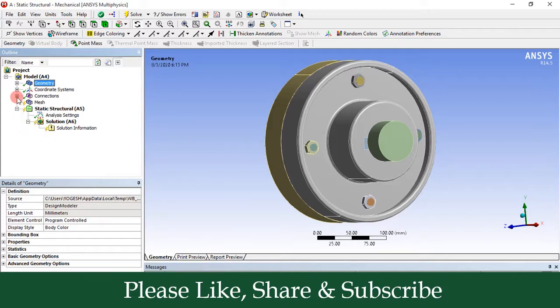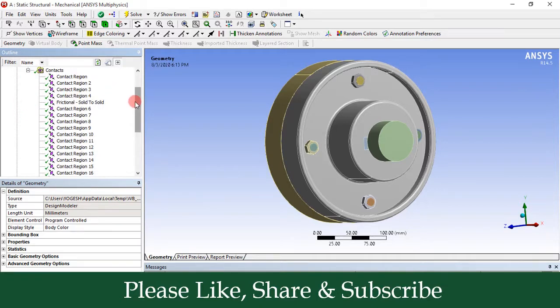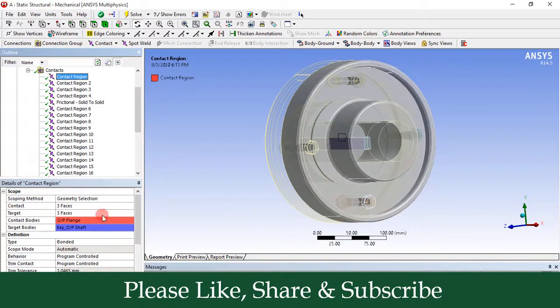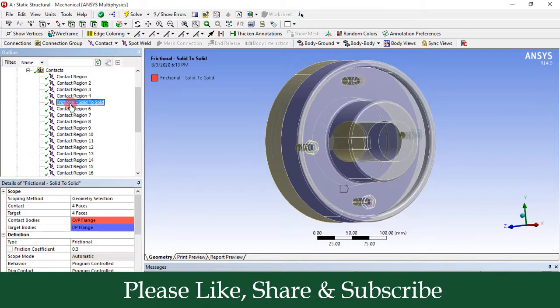So let us go to the connections, expand these contacts. Here the contacts are developed between output flange and key of output shaft as a bonded type. Then second is output flange and output shaft, again taken as bonded. Similarly, other contacts developed are taken as bonded.